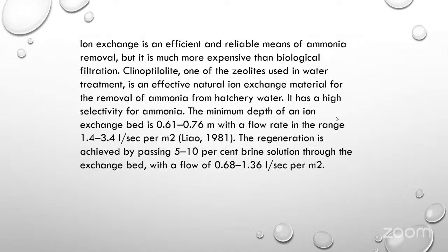Then ion exchange. It is an efficient and reliable means of ammonia removal, but it is much more expensive than biological filtration. Clinoptilolite, one of the zeolites used in water treatment, is an effective natural ion exchange material for the removal of ammonia from hatchery water. It has a high selectivity for ammonia.